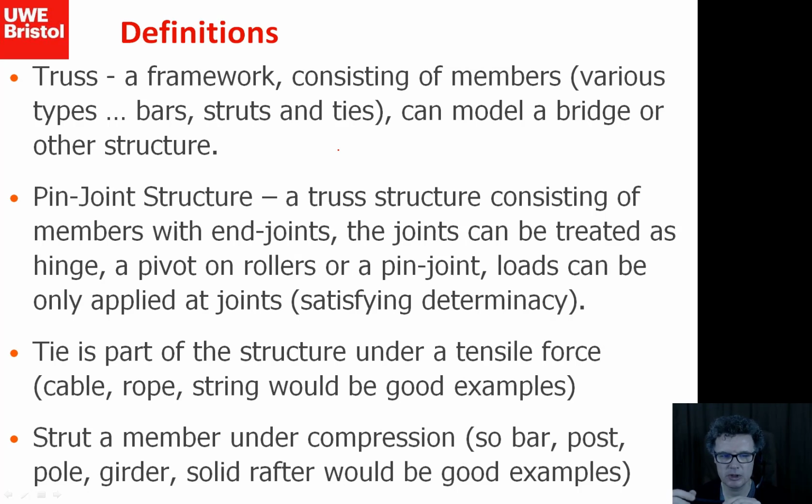So these joints can be treated in effect as hinges, and what we do with these joints is we could stick them onto maybe a surface so that they can only go in a certain direction, or that we could kind of glue them so they can only sort of move around in a certain direction. And this is this term called determinacy. So that's whether, if I've kind of restrained my joints in such a way that if I apply some force, they won't all kind of collapse and move or whatever.